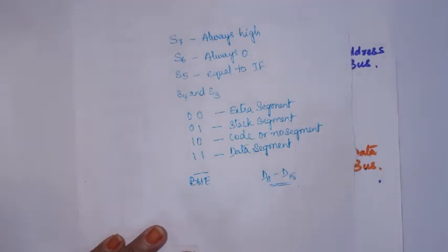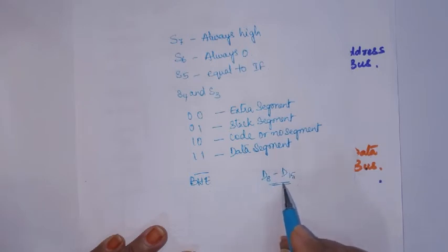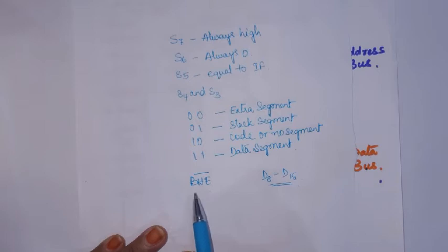For a particular instruction, if it is only a byte transfer from the low order data bus, then there is no need of this, as there is no data on these pins. This indicates that there is data on these pins. To enable the high order data bus, this pin is used. You will understand it clearly when we study the memory organization, the memory bank system.